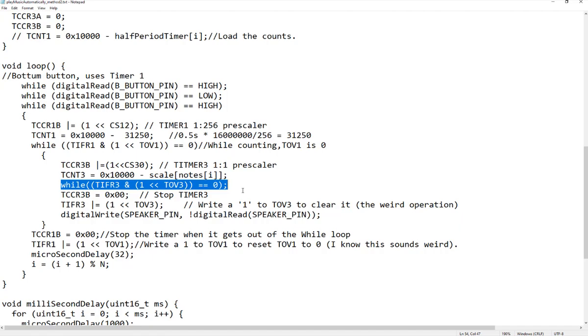So when that line, the while something, that line is being executed, it's waiting there, right? While timer 3 is still counting. Does ISR work? Okay. Of course, it still works. You didn't disable it, so it's enabled. So ISR always works. But how does that work? It interrupts where? Interrupts that while loop, right?